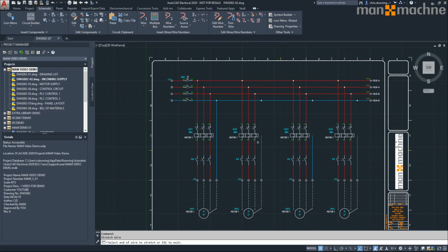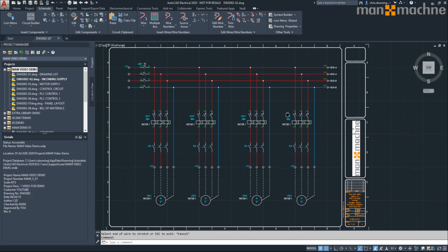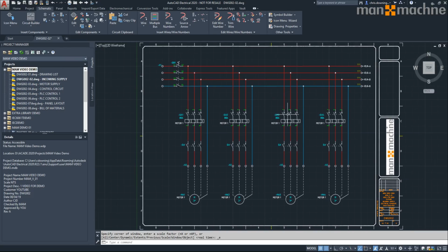I can see that a bit of my wire didn't copy across. Must be two segments of wire, and that's the reason why. I'm just using my extend tool to extend it to the next point. You'll see that this wire is probably made up of two wires, so what I could do is trim out that bit and extend that bit to just make it a bit neater. I can also copy it to a clip and paste it onto another sheet,